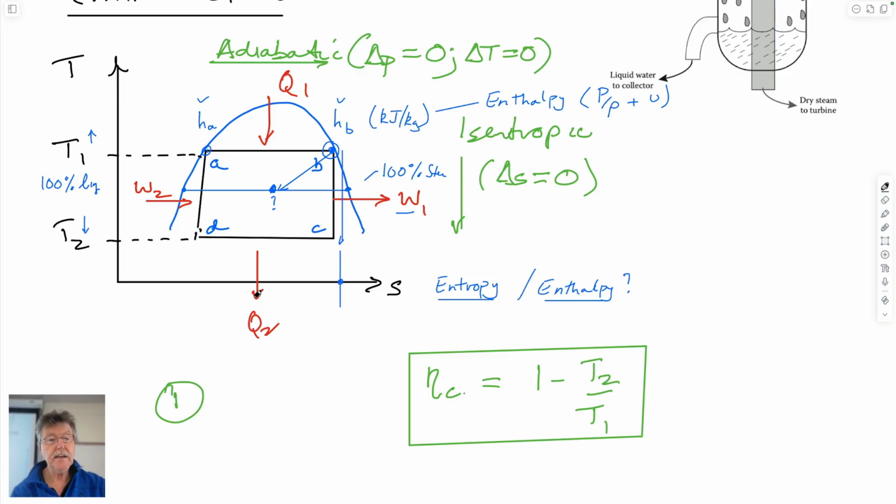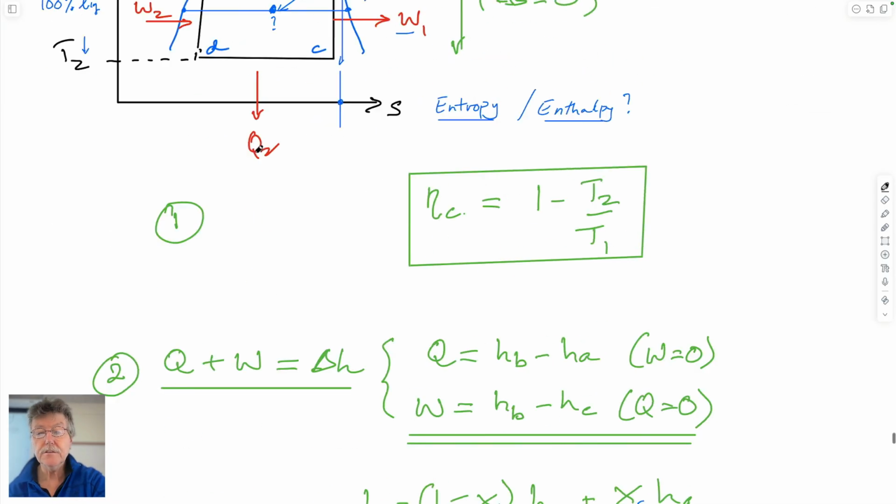So you're taking heat energy out of it and cooling it, and then you're providing work into it to be able to compress it. So it goes from a gas here to being a high density gas, which is then compressed and is then flashed to isopentane vapor, run through a turbine, and then cooled. So that's kind of the reverse cycle.